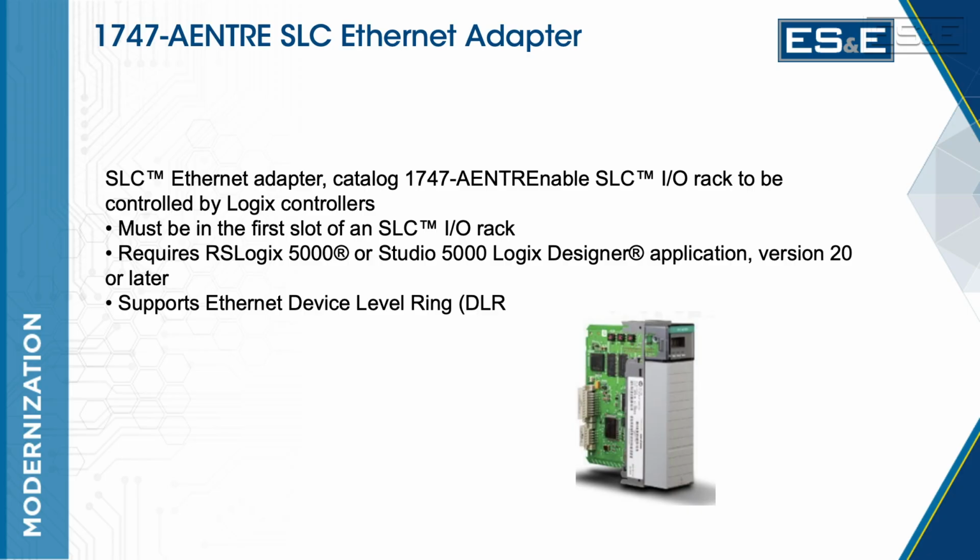In ControlLogix world, you can put multiple processors. It doesn't care. It just goes on the backplane. Especially 2, 3, 4 are the same, right? Yeah. So just to make sure which one he's going to replace or change. Yeah. So I'm just trying to see how the position is denominated physically. Yeah, it doesn't change.